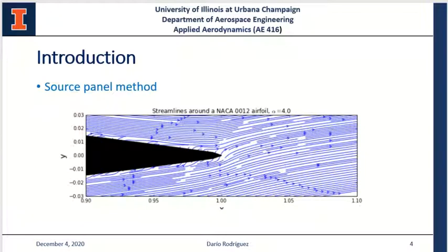If it is true that the source panel method can help us to describe the flow field of symmetrical airfoils, since we don't use circulation, we are not able to calculate the lift. So to solve this issue, we need to add a circulation strength to the source panel method we previously described. And we then take advantage of the fact that potential flows can be added to describe the flow behavior around airfoils, which are also subject to a certain angle of attack.